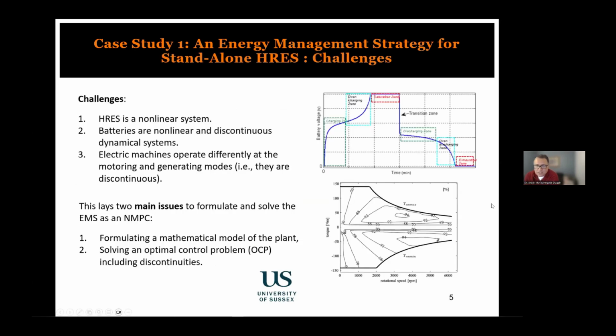The challenges of such a system are that, first of all, of course, it's a non-linear system, but more than being non-linear, at least two components of such a system are discontinuous, meaning that their operation changes completely with respect to some other events in the system. For example, the battery is one of those discontinuous systems. The behavior of a battery when it's charged is completely different from its behavior when it's discharged.